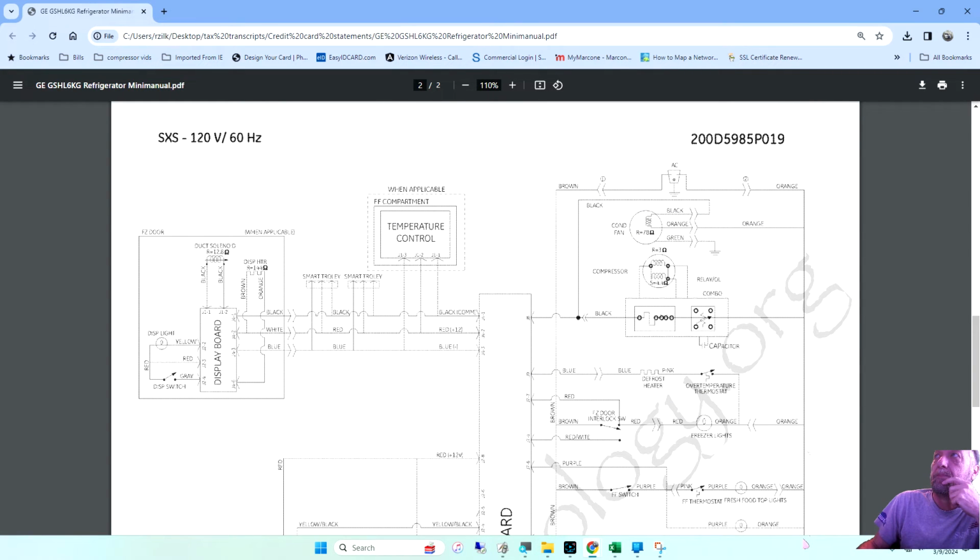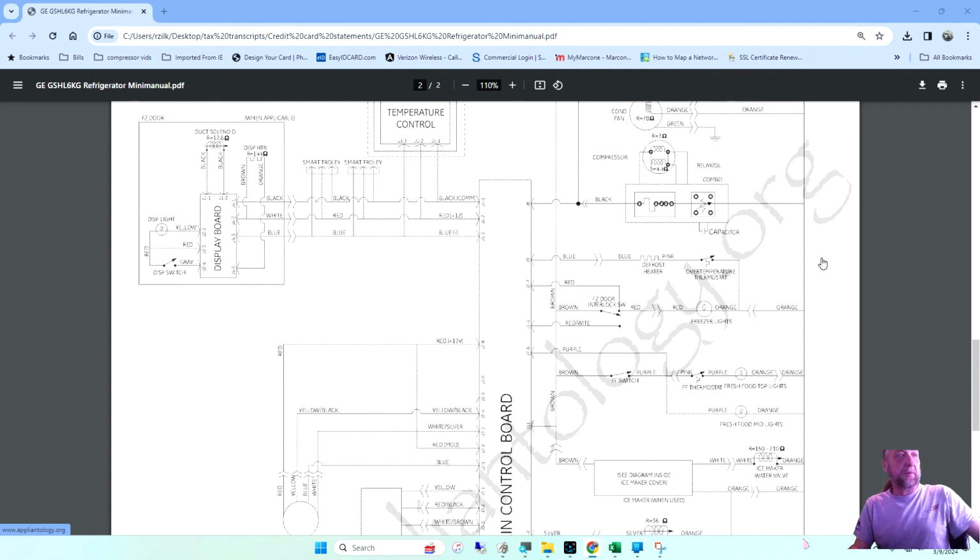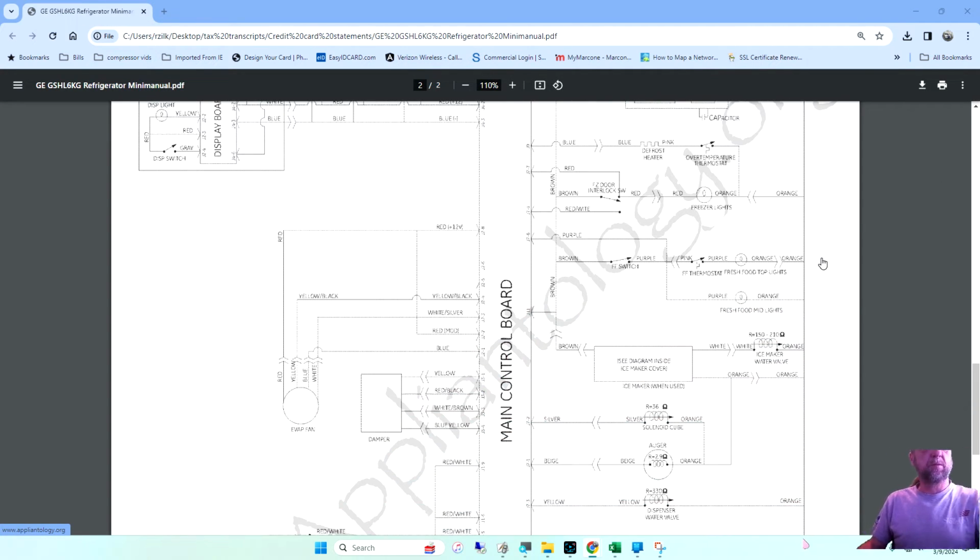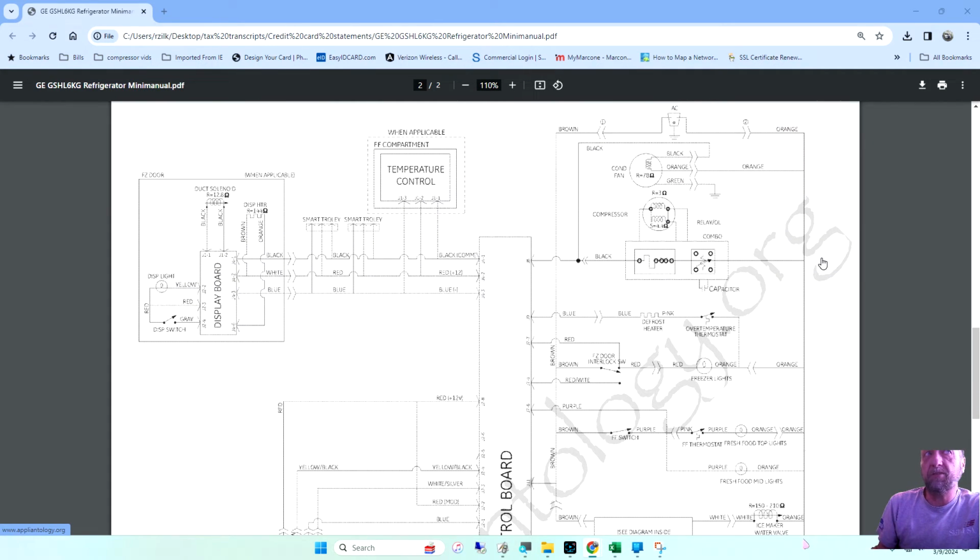So I removed the evaporator cover. I waited until the frost started coming back up. The frost came up to like 2/3 of the evaporator. So I said, okay, I think I'm good now. So I started trying to put back the cover at the back, and then the compressor stopped. Well, I couldn't tell you what that is. I guess the first thing you want to see is whether the compressor and condenser fans stop. Yeah, both of them stopped.